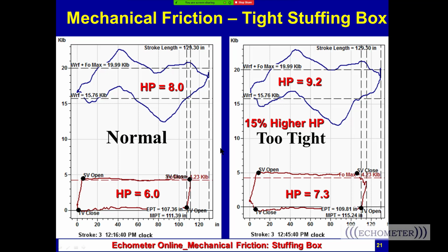This is a well up in North Dakota, and this data came from Ken Skinner. I called Ken one day and said, Ken, I'd really like you to go to one of your wells that has a low fluid level, the pump is full, and then take your crescent wrench and over tighten the stuffing box. And so he put the crescent wrench on the stuffing box at the surface, and he tightened it down until it started to squeal. And now this is the additional horsepower.